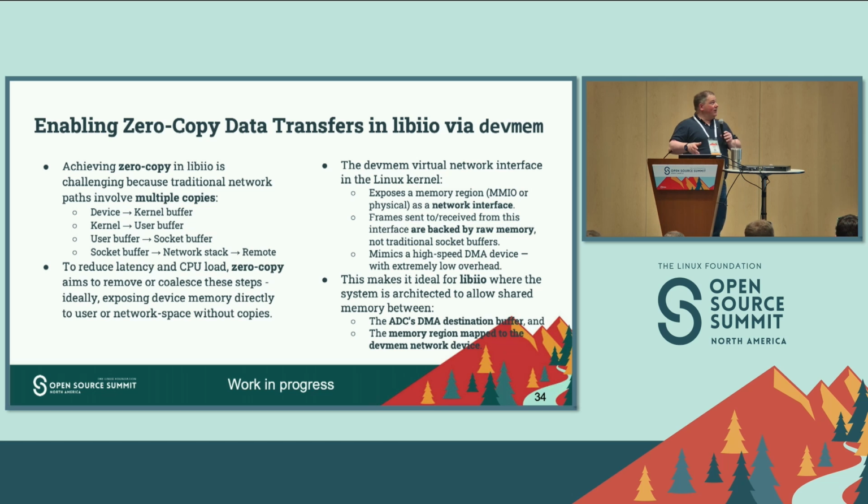So the other thing that we've done in IIO 1.0, or are working on, is use DevMem. DevMem is a concept on the Ethernet side to actually have zero copies in the Ethernet stack. So you can go directly from DMAing ADC data to non-coherent memory, and then that goes right out to Ethernet with no mem copies in the kernel, which is a big, big improvement in terms of overall throughput.